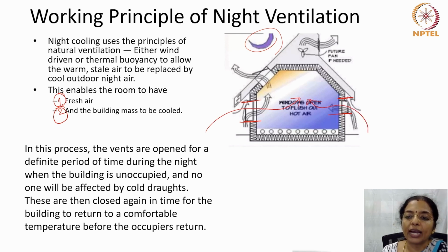The cool air which enters the building lowers the temperature of the indoor air and that is absorbed by the internal surfaces, and as I have already been telling you, warm air rises up and escapes and cool air is retained. And during the day, this must be closed. All the vents must be closed so that the cool air is trapped inside.